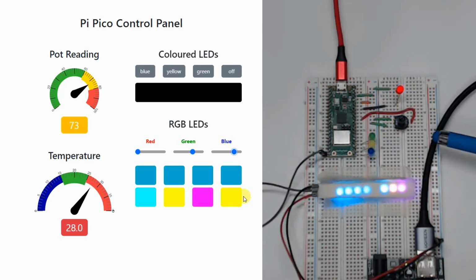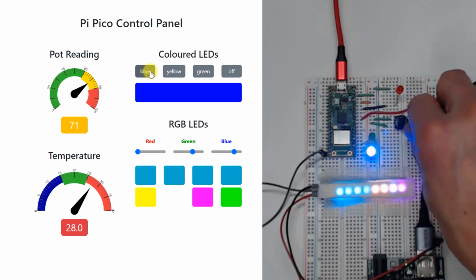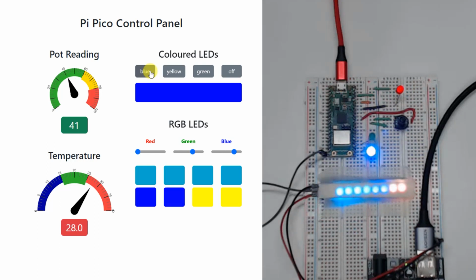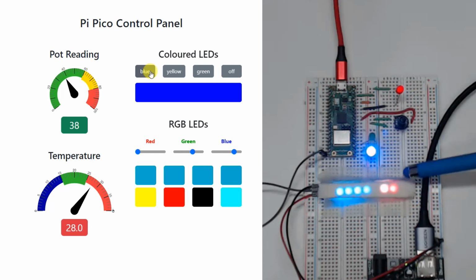So really what's happening then is our web control panel is sending signals to our Raspberry Pi Pico as we click things up here. It is receiving back information when we adjust things like our dial and so on. And then it is running in its own control loop. So again, these are making sure that we're not having any of this blocking code whenever we try and handle our HTTP requests. So our asynchronous web server is able to run these loops while we are doing everything else.